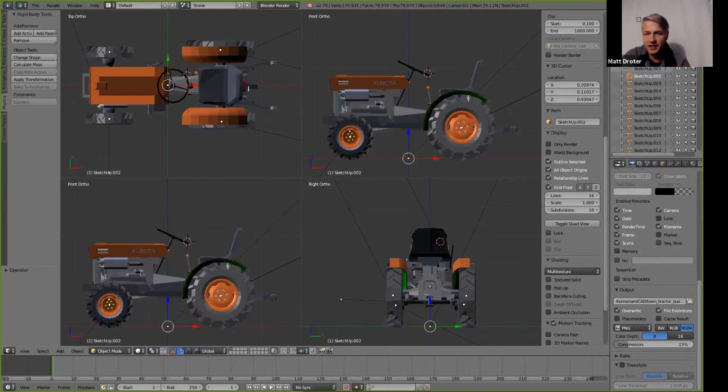I mean, maybe you could redraw it or change that thing around, and then you wouldn't have to rotate the image. But inside of ROS, you can rotate that image wherever you want it. Yep. So that's the reason that we are actually rotating in the Z axis. It means that you will just rotate 180 degrees to make it in line so that the front of the tractor is also in the direction of X. And in the RPY, back to your URDF, that argument is in radians, that's why you put it in pi. Exactly. Yes.